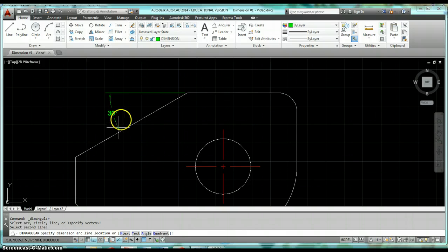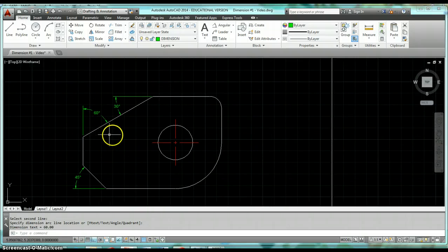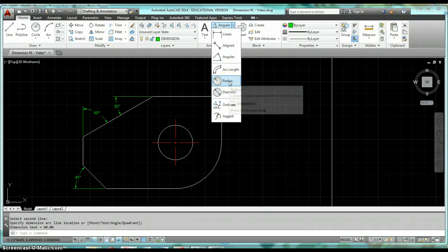So here the one that works best is the acute angle, so just drag it outside the part and place your angle there. You can go ahead and we can try it going the other way too. Click the vertical line, click your angled line, and you can mark that angular distance also. So that's how you create angled dimensions. The last couple are radius.